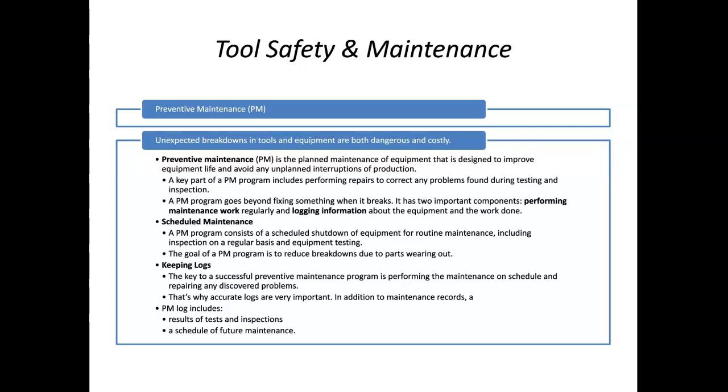And of course, we're going to keep the equipment testing in place. We're going to make sure that if the bearing or anything else is going to wear out, that will be taken care of. But most of the time, when we do that planned PM, it does help us to replace parts before we have a catastrophic failure of that part.